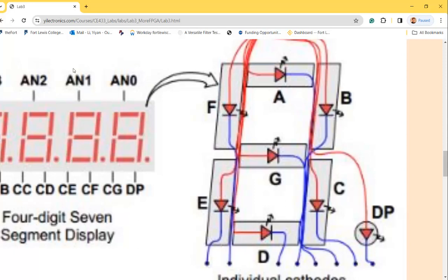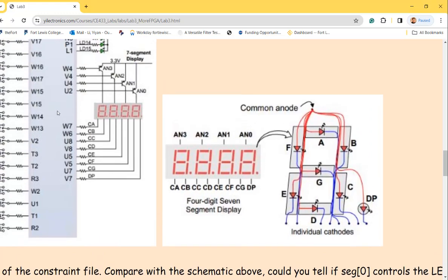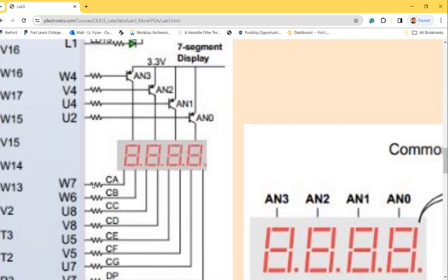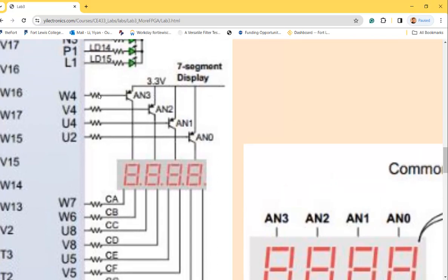Do we have a resistor to protect the LED? Take a look. Do we? Yes, we do here. Right? It doesn't have a resistor inside, but it can connect a resistor outside. Okay? And this resistor is trying to limit the current going into the base of the PNP transistor.